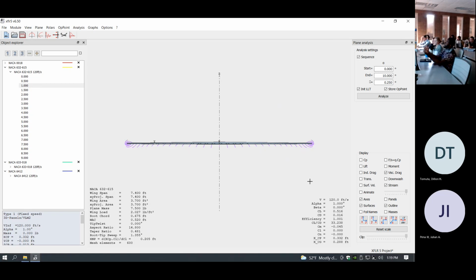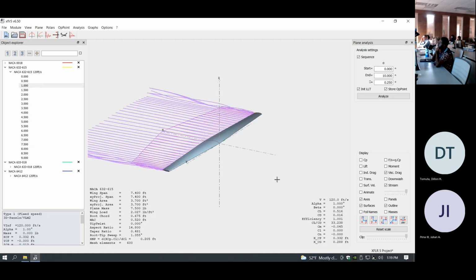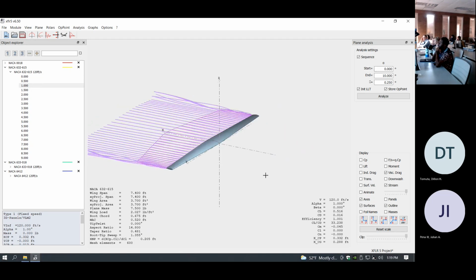Yes, Robert. Since the flow is going behind the airfoil, is the flow negative? Does that make sense? No, what you're seeing is the wingtip vortices formation, not streamlines. This is a frontal view. Go ahead, turn it around, rotate. That was a head-on view. I just wanted to show you how the wingtip vortices are forming, because it's the easiest view to show how the streamlines are being altered as the wingtip vortices begin forming.